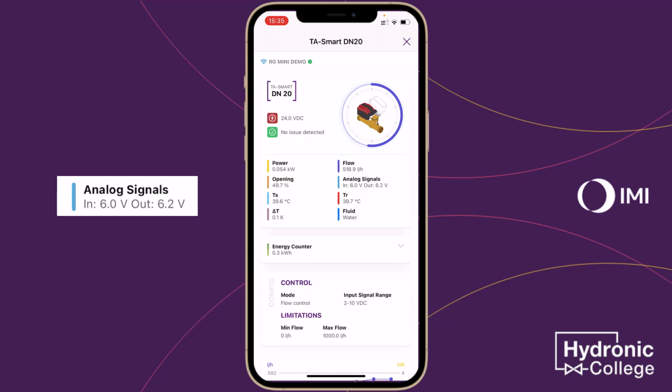Now, watch what happens when we simulate a line break and the input voltage drops below 1 volt. We can see straight away that an error has been detected. This is error 2, line break detection. After the configured delay, control fallback applies itself, in this case to 40%, and the valve will sit at 40% of its setting in the control fallback setting.